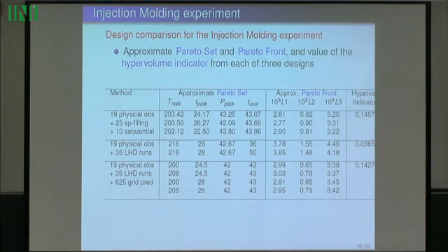So I now have quite a few settings here of the 4 control variables that I can give back to the engineers. It has reduced the ranges quite considerably. This first one, when we started, the range of melting temperature was going from 180 up to about 230, and you can see we've at least narrowed down to a good range being about 200 to 208, and now if they can do another experiment, then that's the range they would look in.